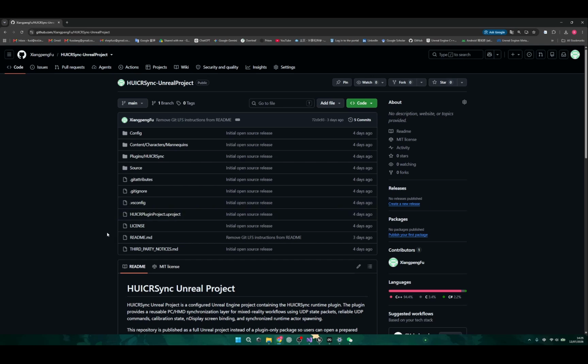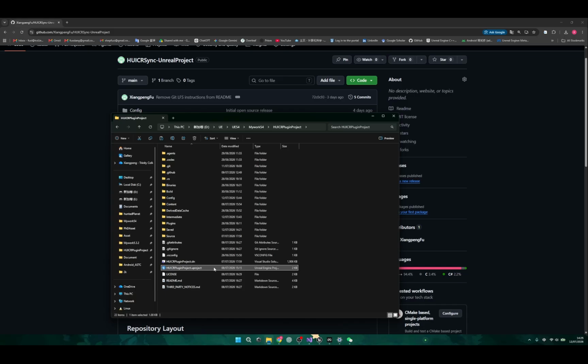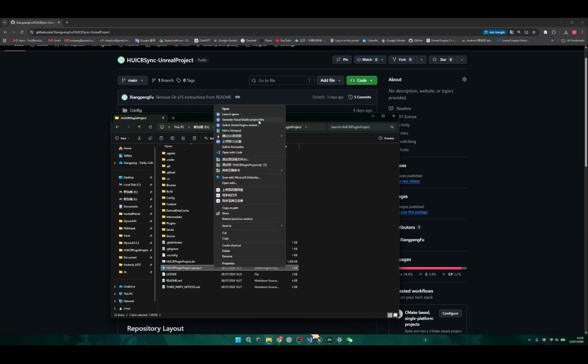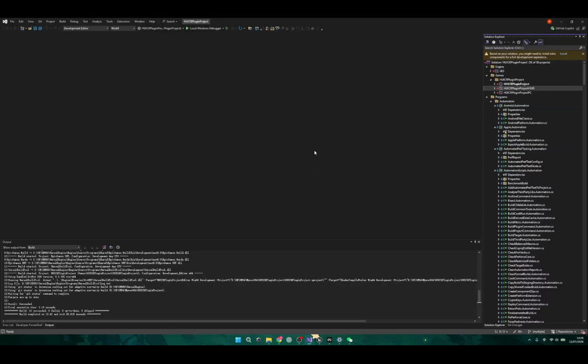Hello everyone. In this video, I will demonstrate how to build and launch the HUICRSync plugin project and how to calibrate the HMD with the PC setup. Before getting started, we recommend following the documentation linked in the video description to download the required version of Unreal Engine and the plugin. After downloading the project, right-click the UP-Project file and select Generate Visual Studio Project Files. Then, open the generated Visual Studio solution.